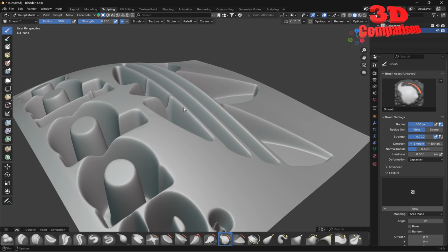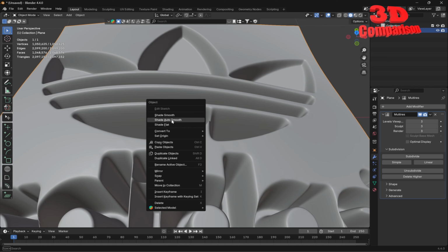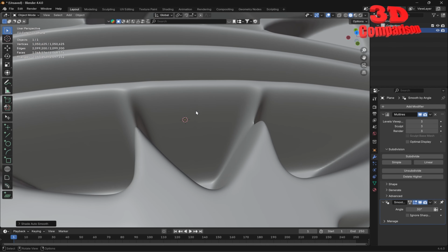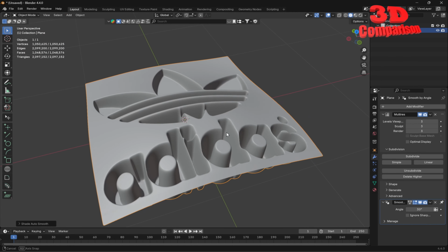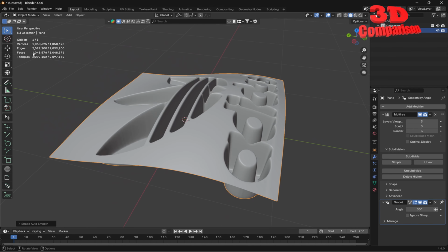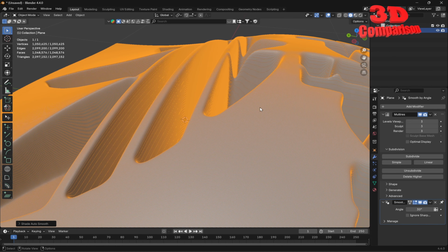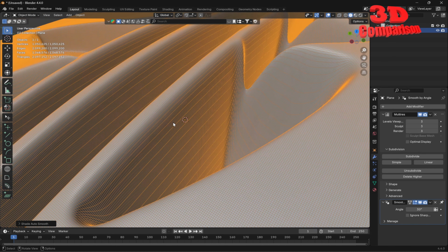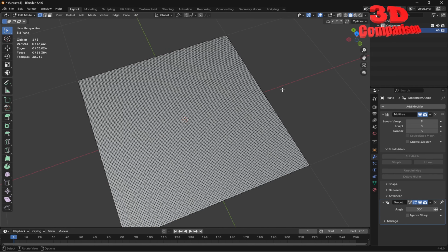If I will go within layout, I can also do some changes to the auto smoothing over here, and we're going to see that now the surface will be a lot more smoother. So the same principle will also be available within CATIA. But for this subdivision, in order to work, we see over here on the statistics that currently this mesh will be defined by 2 million triangles. That means if I'm going to zoom in, I will enable the wireframe. We're going to see how fine that mesh will be in order to have those elements, let's say, added to the 3D model.